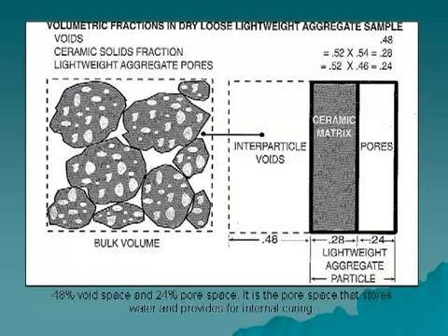Before we move on to quality assurance issues involving lightweight masonry, let's spend a few moments understanding how lightweight aggregate performs in a concrete mix design. In the picture on the left, we view a magnified view of lightweight aggregate particles that are confined to a certain volume. While the different sizes of the particles seem to nest as they occupy space, they still leave interparticle voids. In this example, the voids between the particles are calculated to occupy 48% of the volume, as illustrated by the graph on the right.